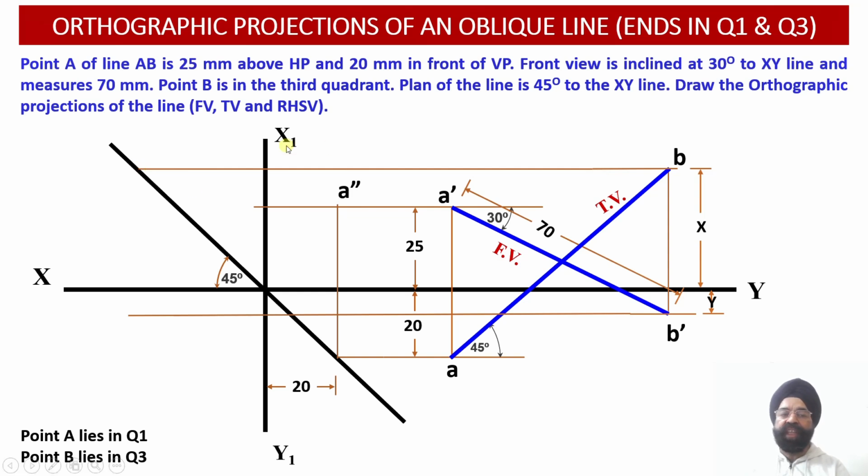And now from this particular point corresponding to the point B onto the transfer line, we have to draw a vertical projector line in the downward direction and keep on extending this projector line till this vertical projector line intersects with the horizontal construction line which we had drawn through the point B dash over here. So wherever the intersection of these two projector lines we are able to obtain, we will be able to obtain the location of the point B double dash over here.